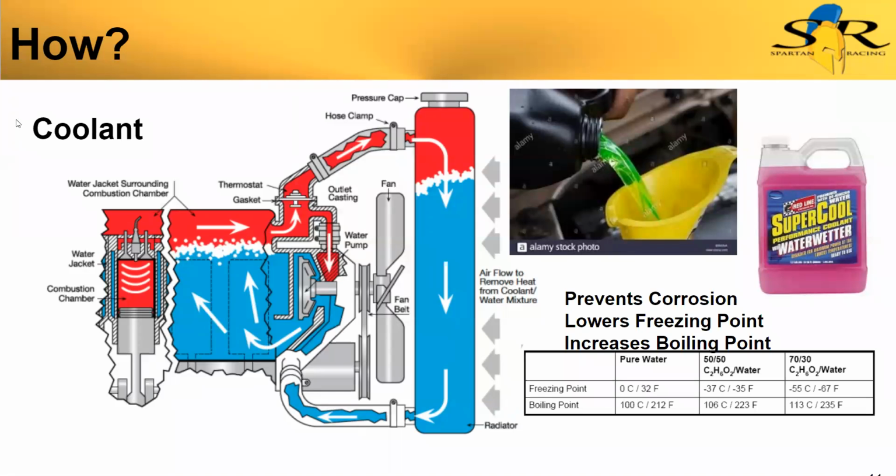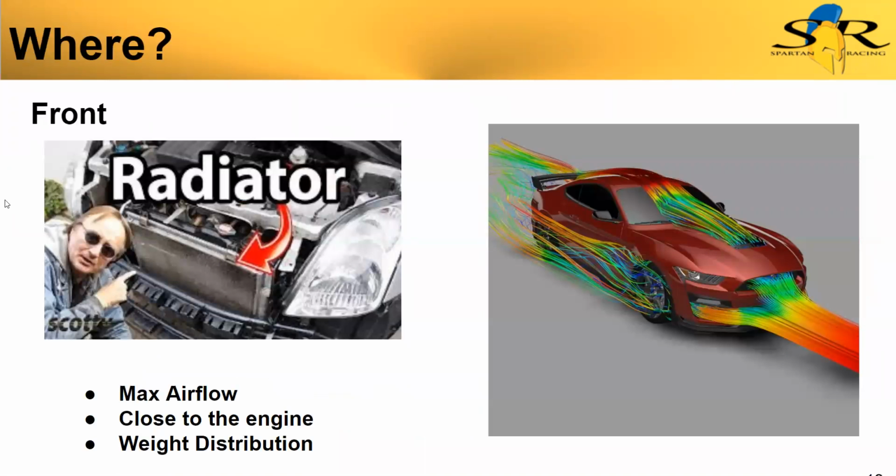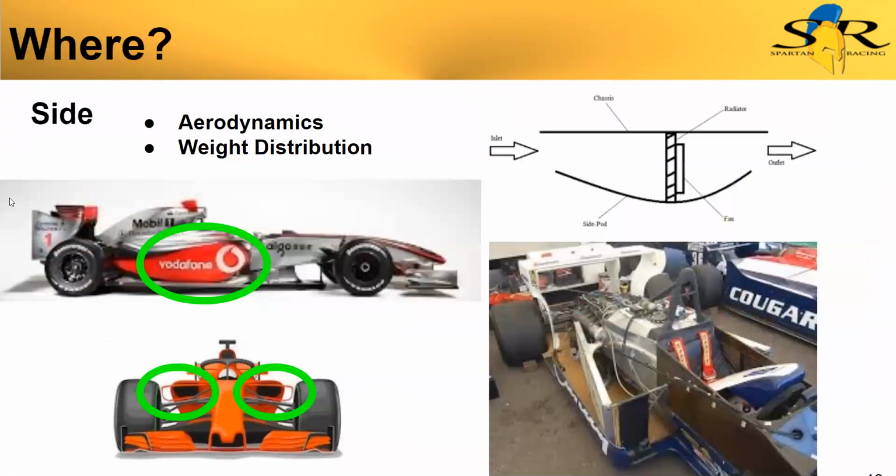It's going to add a lot of thermal resistance, and that's something we'll talk about a little more next time in the design part. But it's good to say, don't just run tap water or any old water through your system, because those minerals will accumulate and clog your radiator and cause things to corrode.